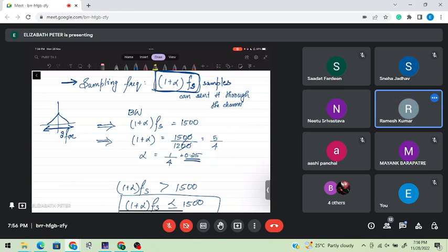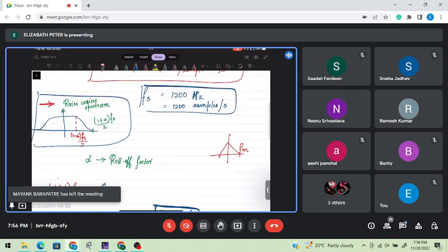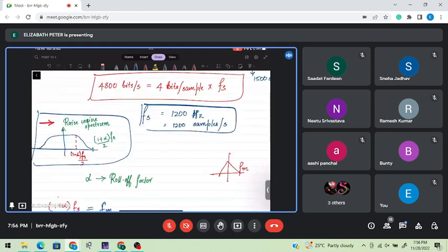Madam, can you say something about the raised cosine spectrum? Okay, raised cosine spectrum. In the previous question I told that the sinc pulse is the pulse shape that uses the minimum bandwidth and satisfies the condition that the summation over n of P(f - nfs) equals a constant, that is the zero ISI condition.